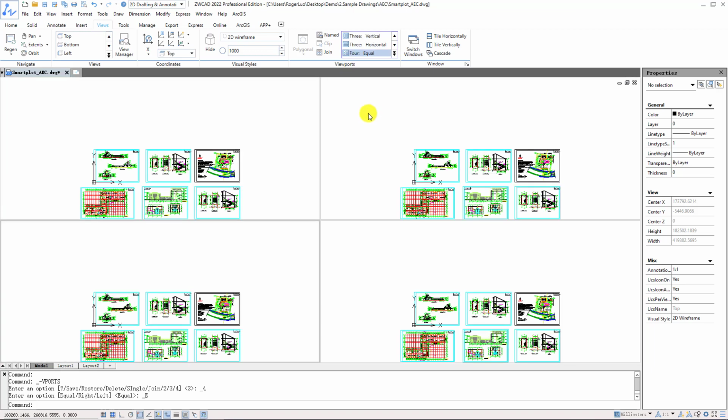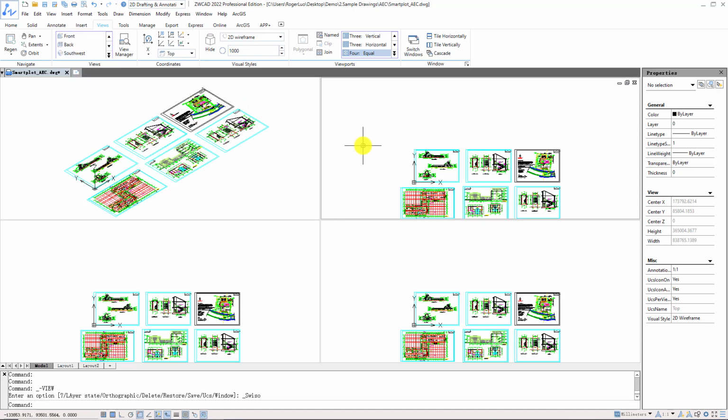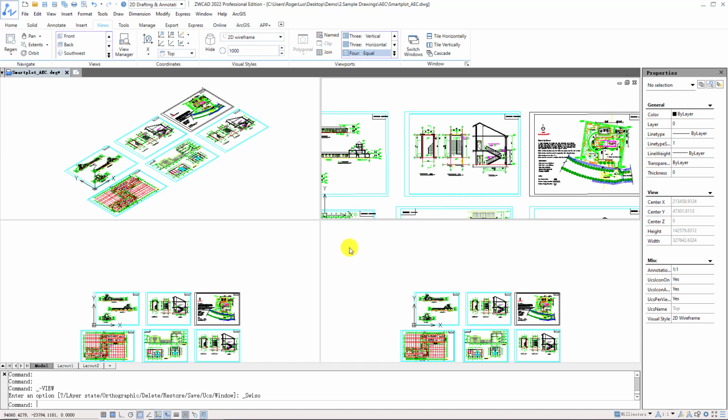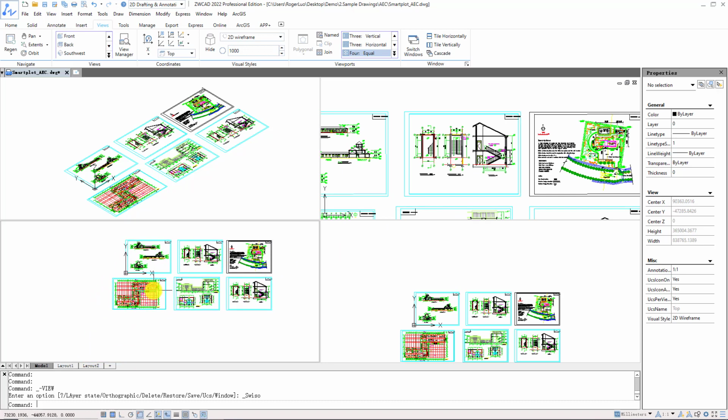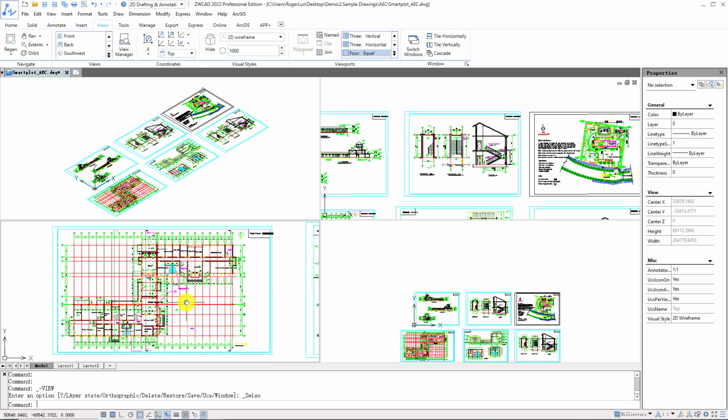Click in the new port. You can apply preset views or your customized views to the viewports. Multiple viewports provide you convenience to look at the drawings or model from different views in model space. There are two layout sheets provided by default.